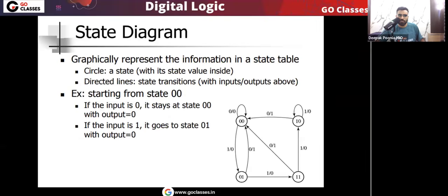In the previous lecture also we have seen this. I told you that when we have external input, then how to make the state diagram? Very simple. In the circles, or I can say the nodes, will be the state only. The nodes will be representing the state only. So for example, if you have two flip flops, then every state has 2 bits. Okay, let's assume we have two flip flops.